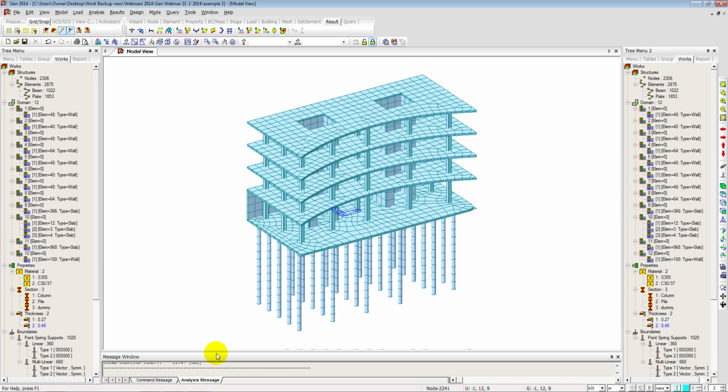I do apologise, we had a few questions come in, so I'm just going to quickly rattle through them. While we were doing the piles, this must have come in. So can we do raked piles? Yes, we can do raked piles, so you can do a pile at any angle. It's just considered a column. Can we do pattern loading? Unfortunately, we can't do pattern loading in terms of automatically defining it, but we can select an area and then carry out the patch loading on it.